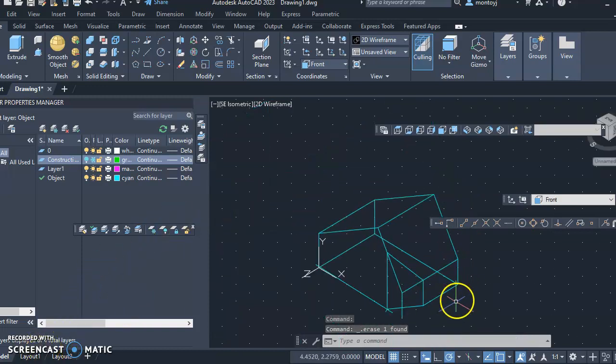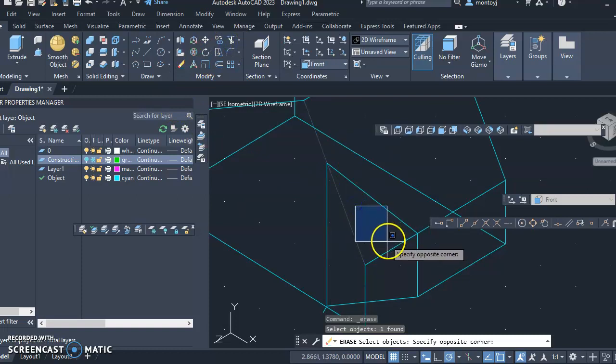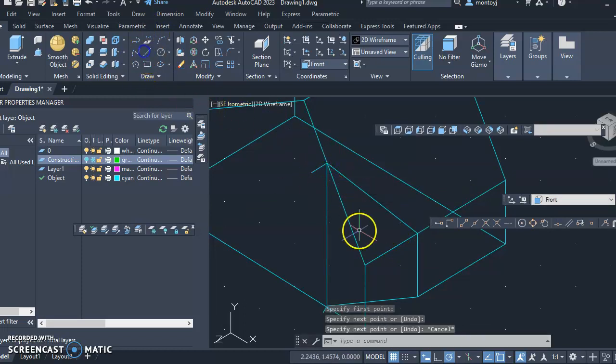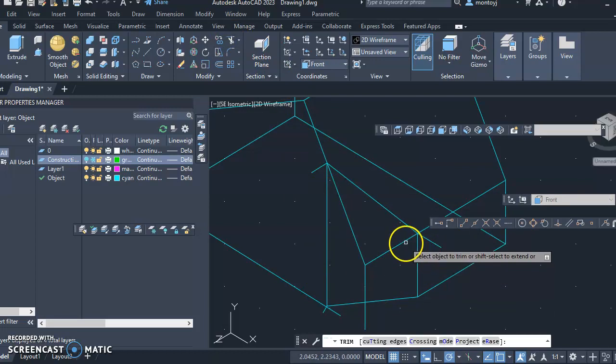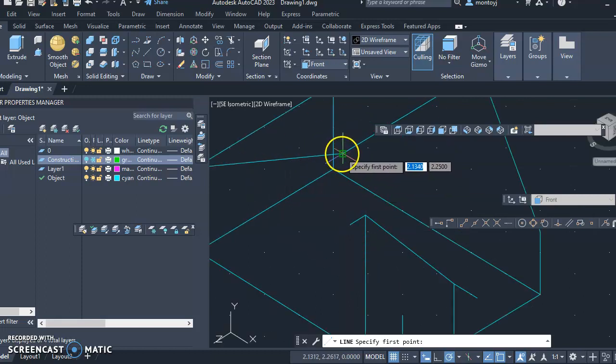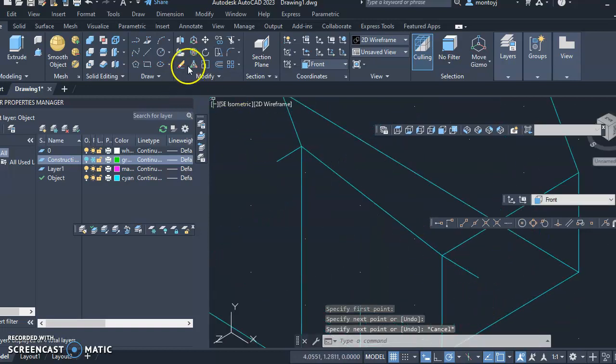Okay, looks like we're getting close on our time. I really want to see if this is going to work out. Let's try a trim on this. No, won't take a trim. Try my trick of putting these little nubs in the hopes that it'll take it. Try a trim. Well, I could do this. I could try and save myself. It's all about saving yourself on this drawing. Recreate that. And then recreate it. So I saved a vertex that I could anchor onto in the future. Okay, and now I can take away these.